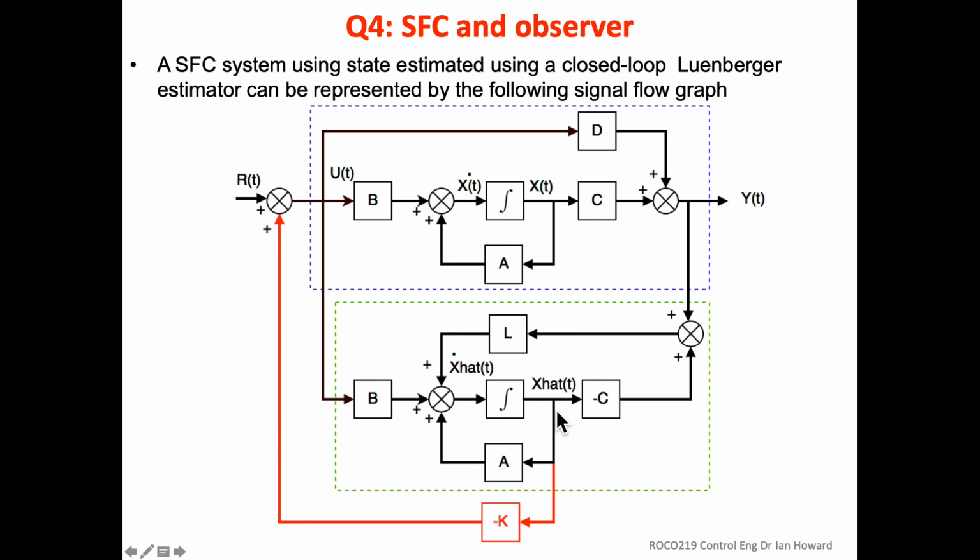So now what we do is we calculate this predicted state X hat, and we use the predicted state in the state feedback. So X hat gets multiplied by -K, and that gets fed back to the beginning. And if we want, we can put the reference term in. So this bit down here now corresponds to adding on this Luenberger predictor, and we're using full state feedback control from the estimated version of the state of the system.